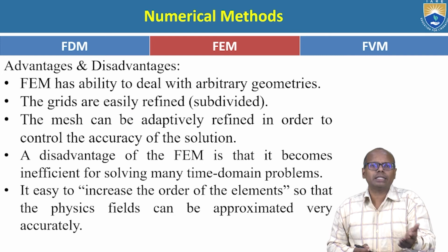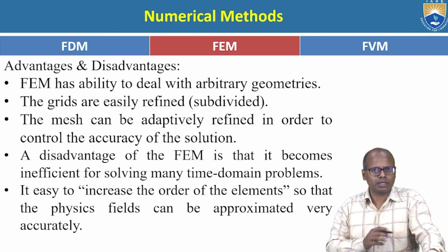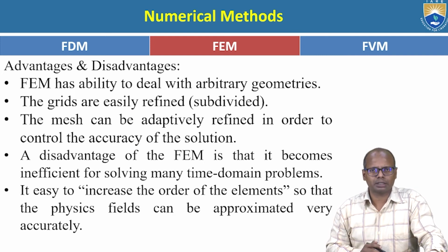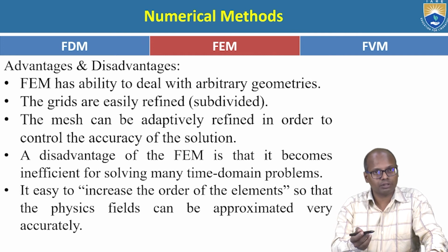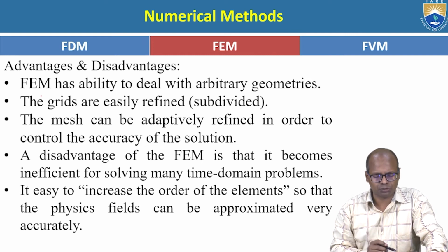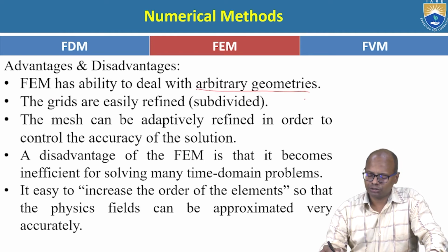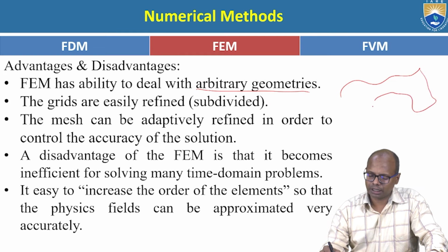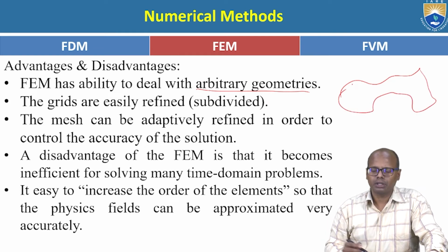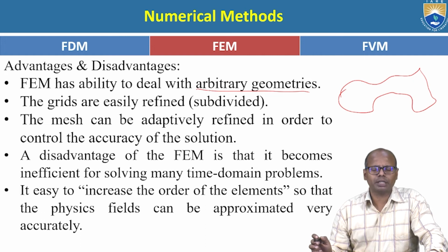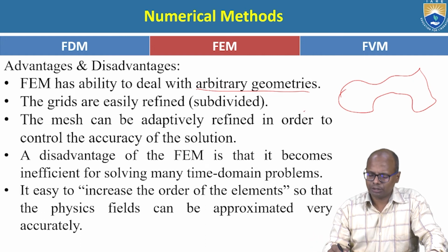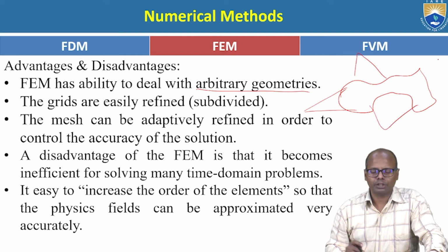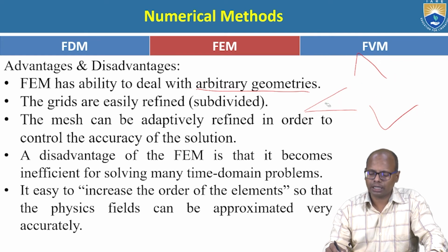Now, what are the advantages and disadvantages of FEM? I cannot say FEM does not have any disadvantages. It has a lot of advantages and disadvantages also. The main advantage is arbitrary geometries. The geometry can be of any shape like this. Any shape of geometry can be there, and it can have sharp edges also like this. Any shape, this FEM can be applied with little effort.